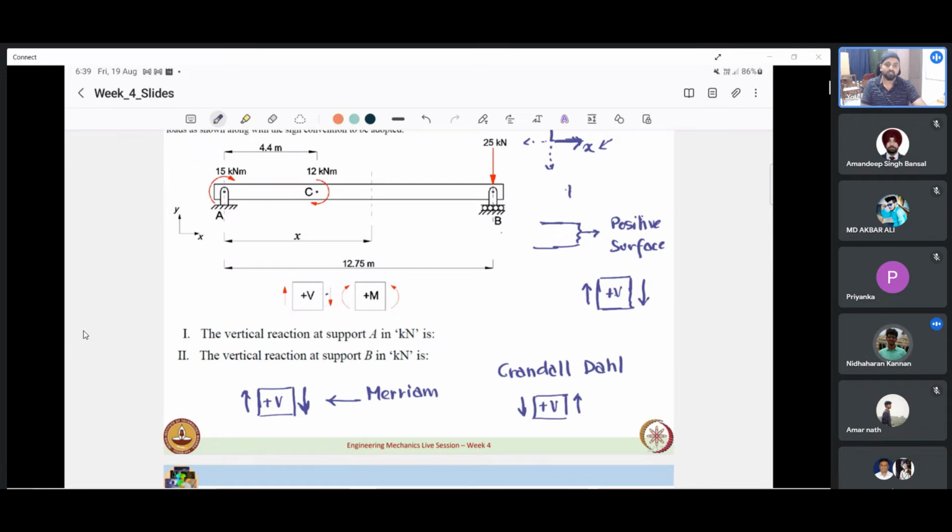We are doing it for the sake of understanding. That should not in any way change the physics of the problem, because we are all open to interpretation and we may develop our own conventions, but ultimately the physics should add up, which it would. If you solve the question with both, the values will still come out the same. The only difference is that the shear force will be the exact mirror image about the x-axis, but the interpretation still remains the same. I hope that is clear.